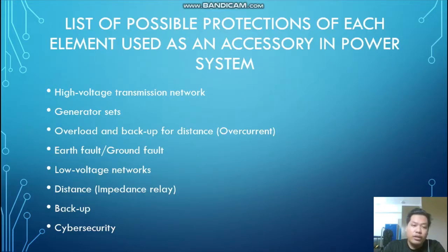And the second one is time overcurrent, TOC. Time overcurrent protection operates based on a current versus time curve. Based on the curve, if the measured current exceeds a given level for the preset amount of time, the circuit breaker or fuse will operate.